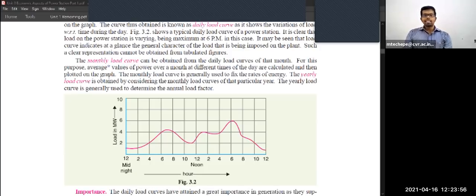By analyzing that, you also have to think about how we can reduce this peak load. Some lights and fans are switched on unknowingly by somebody. If you switch those off, then after one week you again note all your readings and plot them again. That way, you can also reduce the electricity bill for your home.